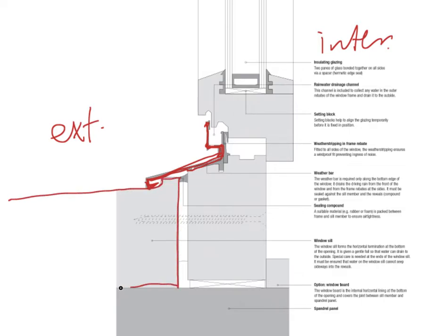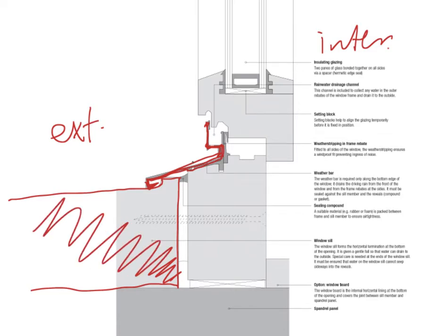That's the windowsill. Here it's a solid material, and again that weather bank is protecting against rainwater or any other kind of thing seeping in. There's an additional sealant in between the frame and the windowsill as well, making sure that it is properly sealed off, but also giving it a bit of a tolerance, as you can see here.